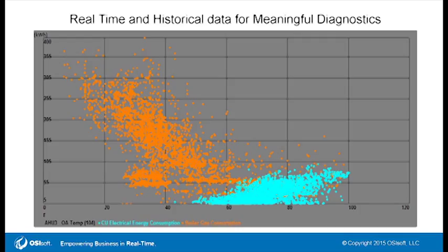But in this case, just by looking and seeing this problem, they were able to retune the two systems and make it much more energy efficient by taking this middle regime here and using outside air. So they would neither heat nor cool, right? And drive that.